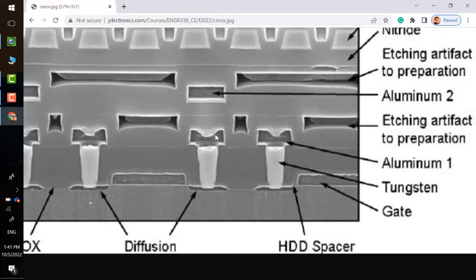Oh, for vias? Oh, I see. So it's able to hold more metal in there? Not sure. Oh yeah, this is metal too, right? Yeah, it doesn't have that shape. So probably this one has a via somewhere else, connecting to metal 2. Otherwise, you have metal 1 here not shorted to anything. It's not making sense either, right? So it's probably at some point shorted to metal 2.